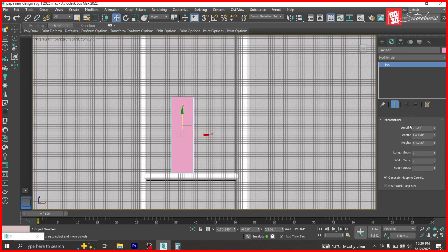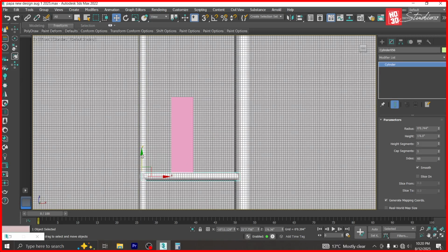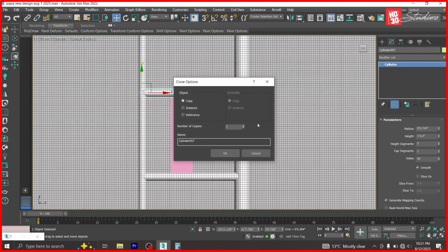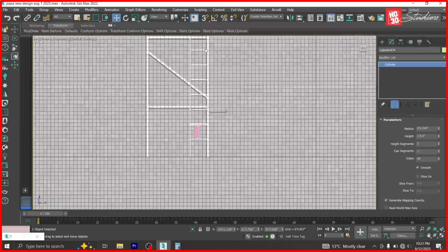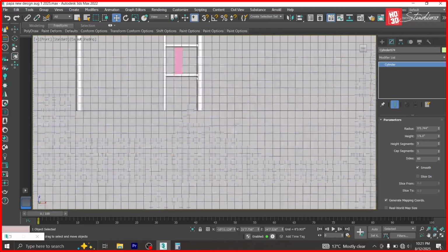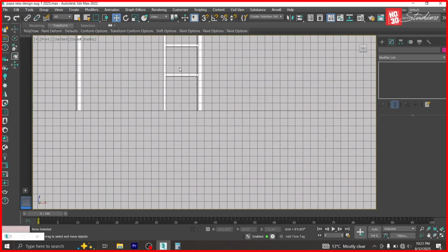It has converted it to fractional inches, but if it were decimal inches, what you would see here in the length would be 1.16. Now I take this guy, I hold shift down, and I drag up to this point. Then it asks me, do you want to duplicate? And I say yes. Click create 18 pieces, 18 versions of it. Good. And then it takes it all the way up. Then I can delete this guy.